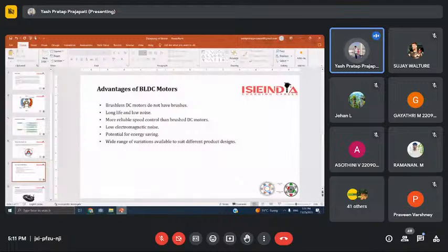The second big advantage, related to the first, is controllability. BLDC motors are controlled using a feedback mechanism to deliver precisely the desired torque and rotation speed. Precision control in turn reduces energy consumption and heat generation, and in cases where motors are battery powered, lengthens the battery life. BLDC motors also offer high durability and low electrical noise generation.